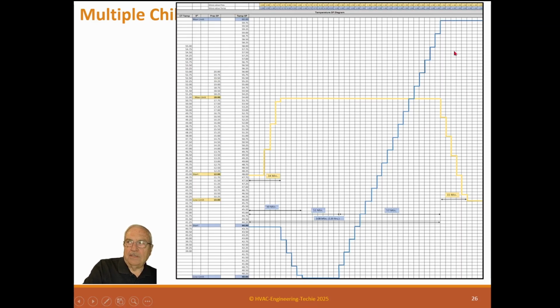This is my handy chart to show the reaction to those parameters we've selected. And this would be the set point of 44 degrees of temperature. So when we start our loop, we get a 6-minute dead band right here. So we get two 3-minute cycles. It does nothing. And then in the next cycle, it says, wow, I've got a bunch of requests.